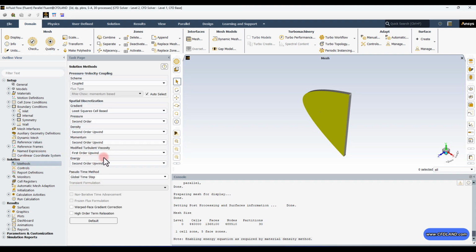And above all of it, it's the methods tab. So in here, we've got 4 different choices provided by Ansys Fluent. And in this simulation, regarding the convergence of our model, I prefer to use the coupled algorithm. So you may wonder what the coupled algorithm is. Actually, it is employed for the pressure velocity coupling scheme because it can solve the momentum and continuity equations simultaneously in a coupled matrix system.